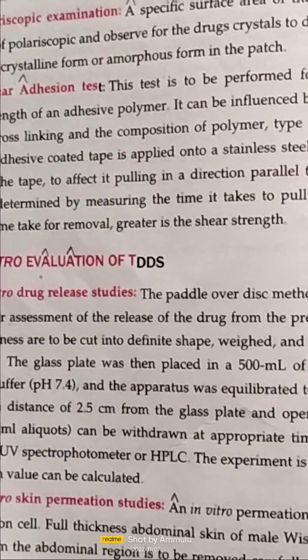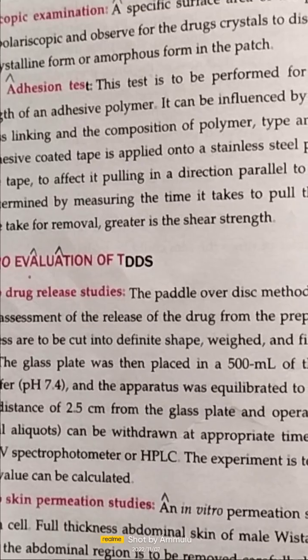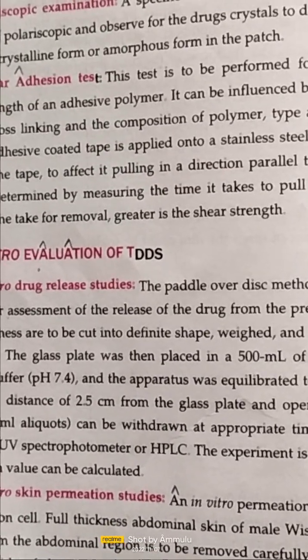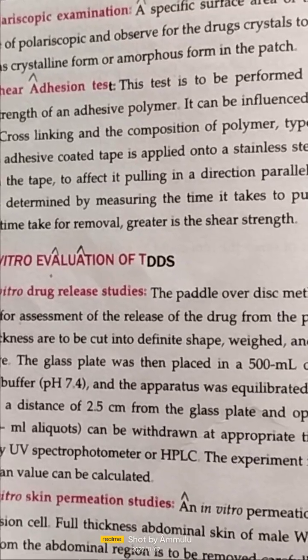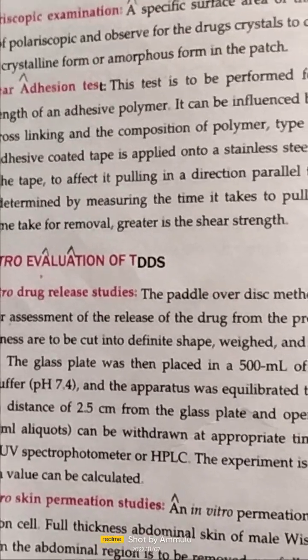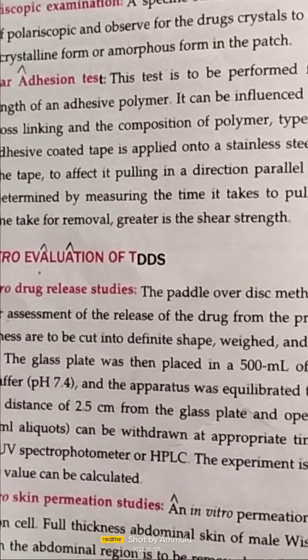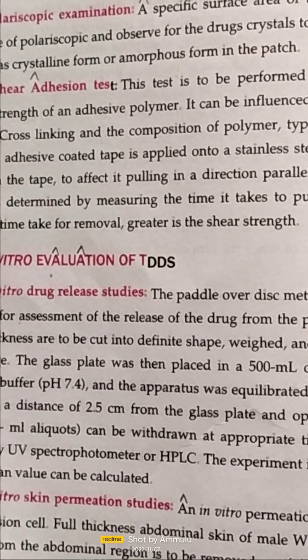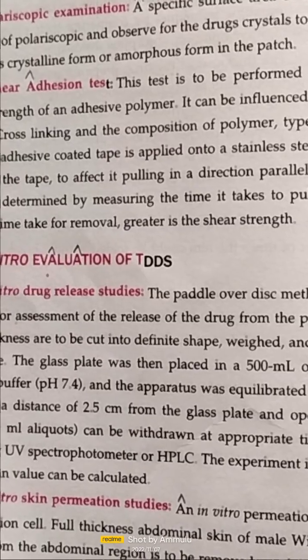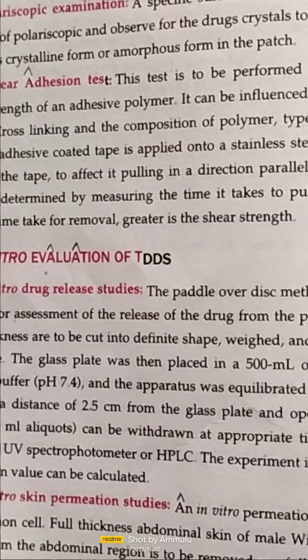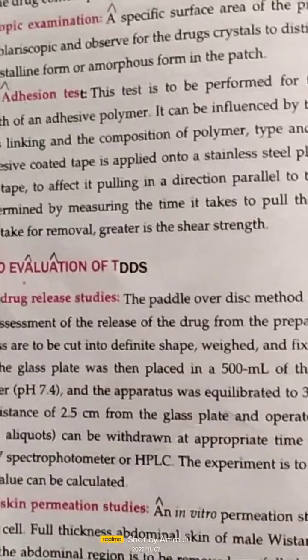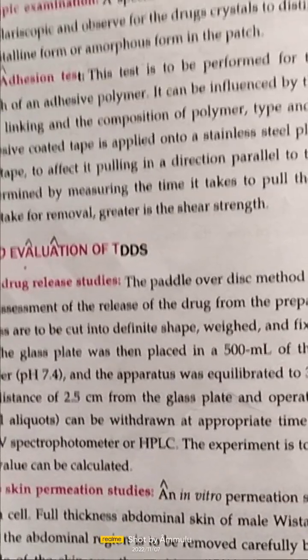And then after that, the shear adhesion test. In this test the cohesive strength and polymer adhesiveness will be measured by a device. It can be influenced by the molecular weight, the degree of cross-linking, and the composition of the polymer. Tackifiers are added to increase the adhesiveness. This is about the methods of evaluation process in